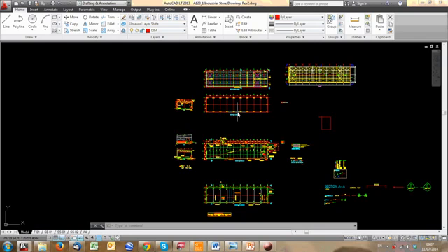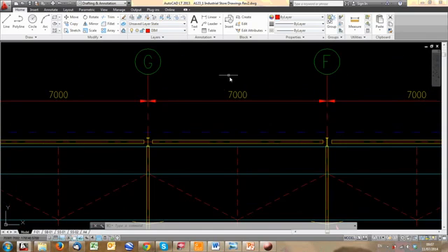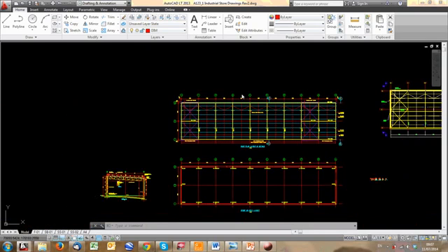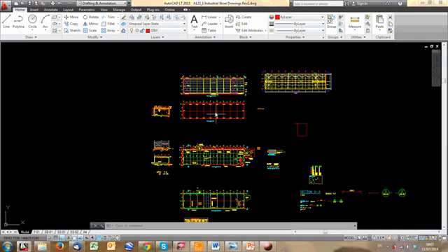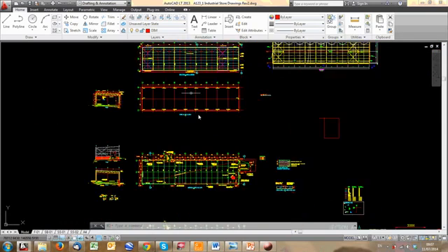What you draw here needs to correspond, though, to whatever units you are using, and that must be set up when you start the drawing, whether 1 unit is 1 inch, 1 kilometer, or 1 millimeter. We are doing everything here in standard metric units, with 1 unit equals 1 millimeter. So that is 7 meters, that dimension you're looking at right now. So be very careful that your units match before you start, that 1 unit is 1 millimeter.